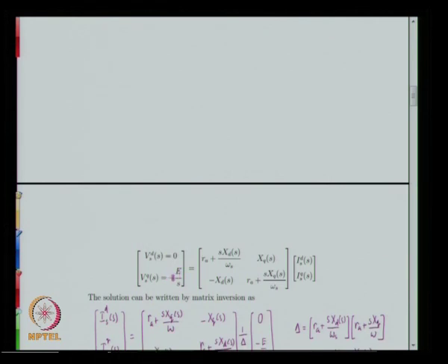The open circuit response we know already, there is no current flowing, and therefore the response to this input, as given by Id and Iq itself, will be the actual current flowing in the short circuited alternator.